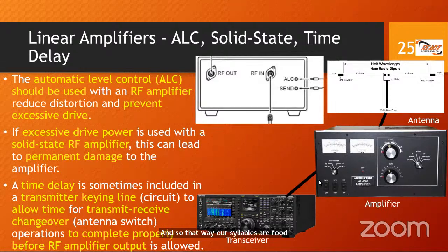So that's again why we've been trained to know about these delays, so that when we key our microphone, we give a chance for the signal to engage and for the antenna switch to move from the receive to the transmit position. We need to allow for that short period. So this is an exam question.